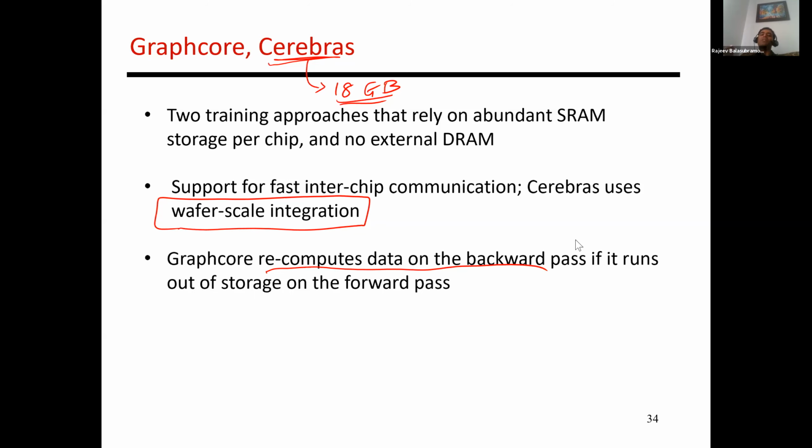In fixed point, all the values are being divided by the same denominator, whereas float allows you to have an 8-bit exponent, and so it can have a much bigger range in terms of the values. For that reason, I think fixed point efforts have not quite succeeded. This kind of relates to that earlier question about whether I can hack into the TPU v1 and somehow make it run a training task. I think this is one of the many challenges that you would have to overcome in doing that.